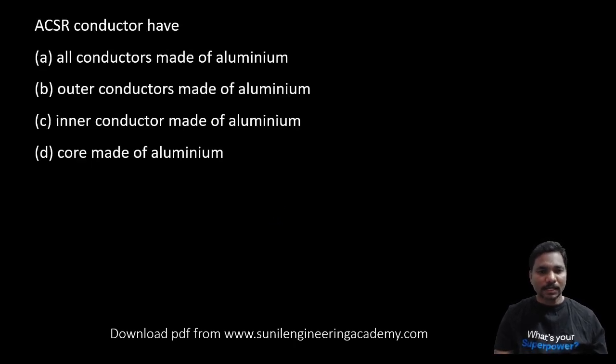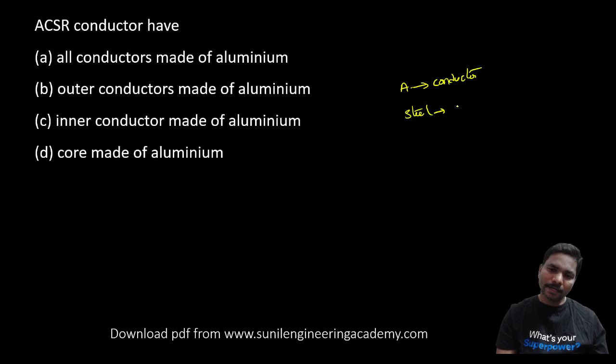And ACSR conductor. ACSR is nothing but aluminum conductor, steel reinforced. Why are we using steel reinforcement? To get mechanical strength.